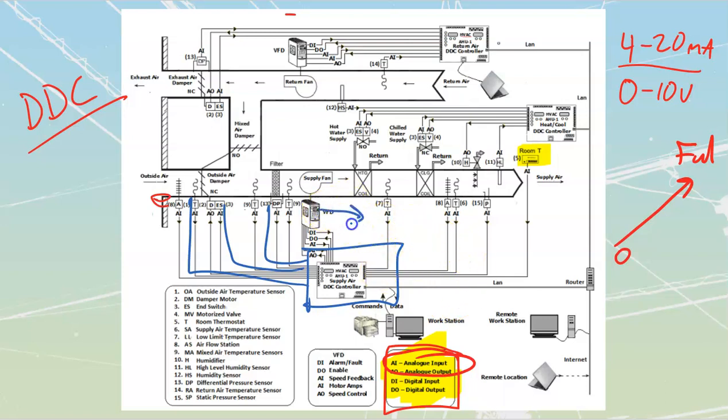Obviously, we would need to run power to the VFD over here. Some of these, like damper motors, we are going to need to run power to them as well. The analog signal will control that. And then we're going to just build those conduit paths. In most cases, they're going to get pulled in by the actual HVAC technicians. They'll take care of all the termination. Or in some cases, they just run all those cables through that plenum ceiling.